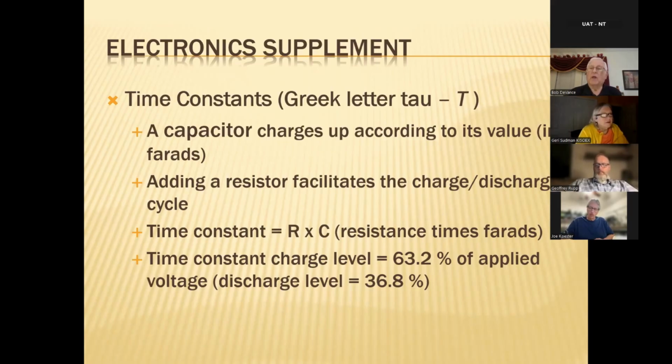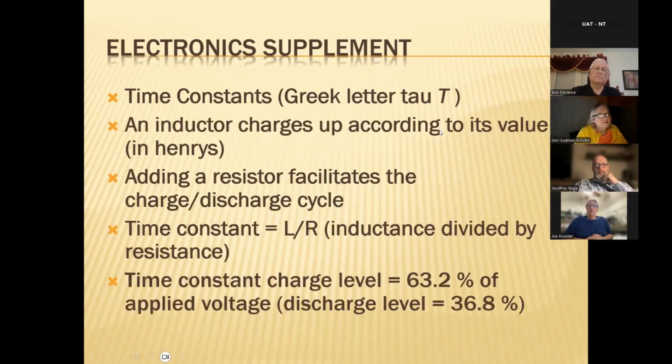Why would we care? Because the time constant is something that we use to determine frequencies that a filter will respond to. We can design a filter easily with a certain time constant so it will filter out or it will enhance or take away from something that's passing through it. So it's important. So time constants. Now, we have a little more on time constants.